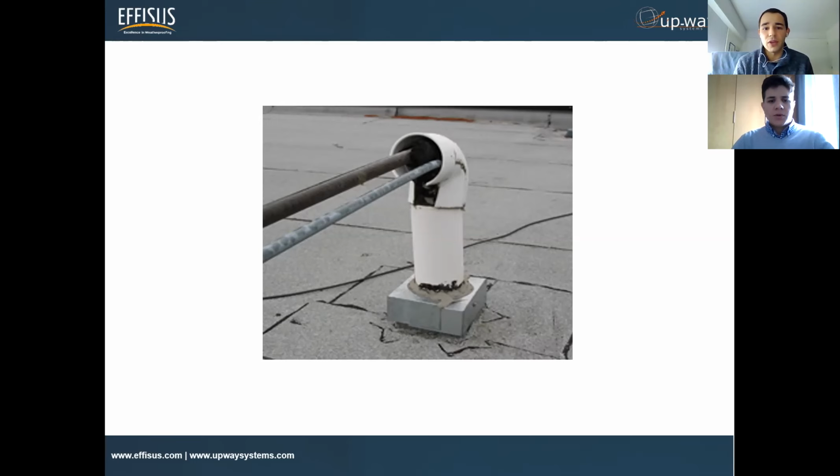What we wanted is just to highlight that this solution, silicone or any type of mastics, shouldn't be just a very quick repair work. Yes, they shouldn't be considered a long-lasting solution or a final solution for this type of finishing or sealing of penetration. For that kind of repair, they work perfectly for a little while. But the problem is people are using it for everything, and there are situations where it's very difficult that it will last a year.